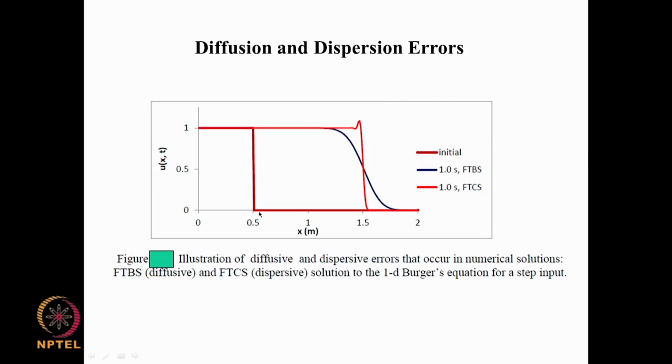In general, for subsonic flows inside internal bodies, probably we do not get these sharp gradients, and we do not have to go for such schemes. Okay, we can probably deal with a second order scheme, and we can get a fairly accurate resolution of the gradient for us to estimate the heat fluxes and all those things.